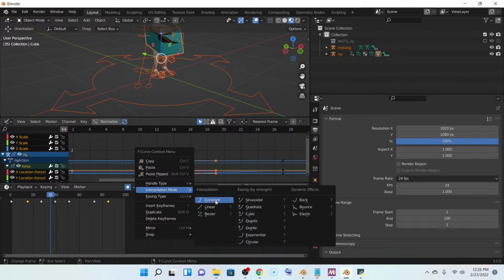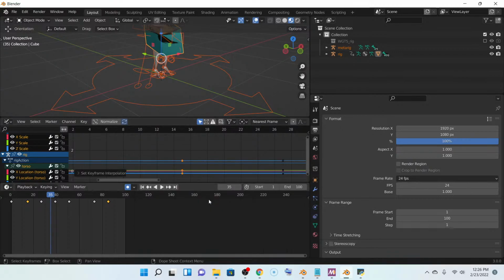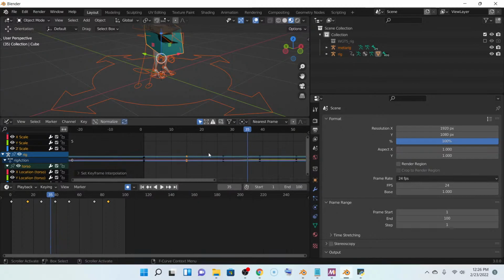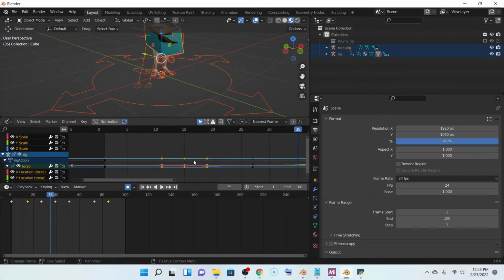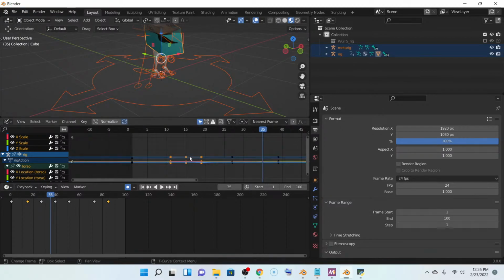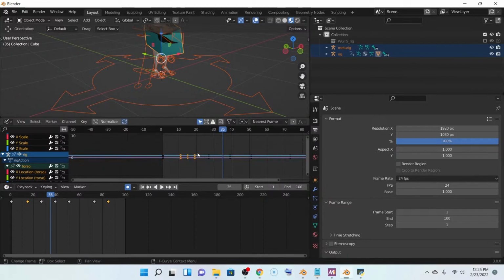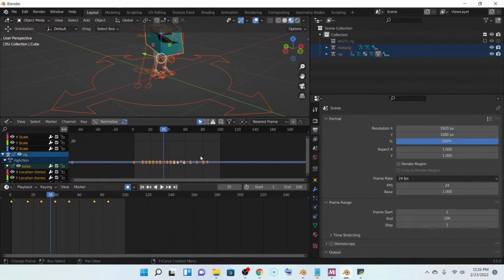So if you want the curvature to look like a square wave, you click square and it will try to create a square wave. Let me hit undo. So it's going to take in between these node points whatever you have selected. You have to select them, obviously. You hit the A key, it selects them all. That selected them all. But if you don't hit the A key, you can hit the left click mouse button and deselect all of them if you want.